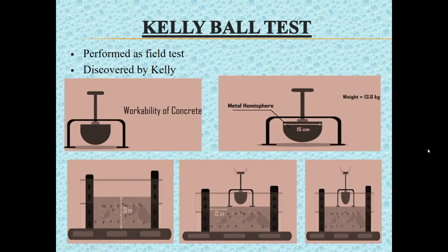The last test is Kelly ball test. It is a simple test performed at the sites. The test has been devised by Kelly and hence known as Kelly ball test. The apparatus involves a metal hemisphere ball of 15 cm diameter weighing 13.6 kg attached to a stem with a handle which is placed on the fresh concrete.